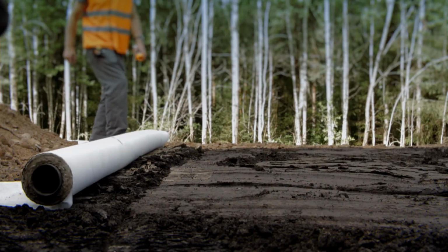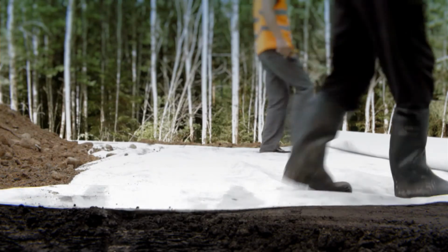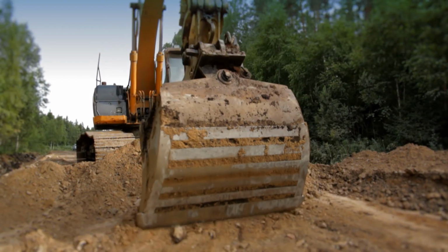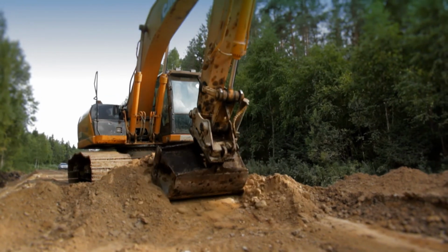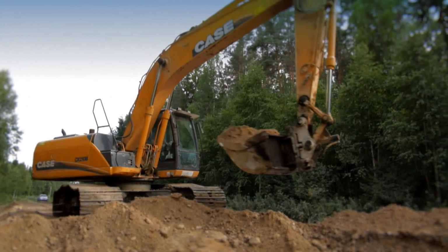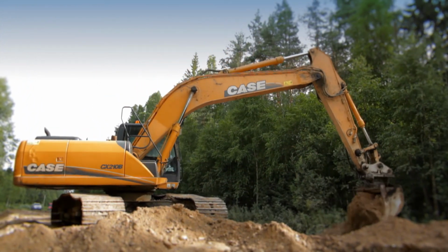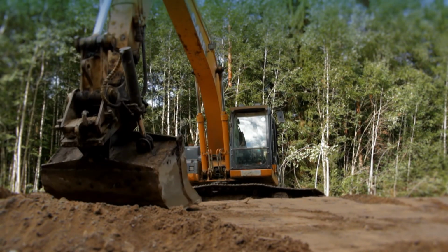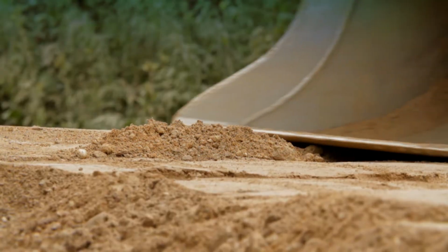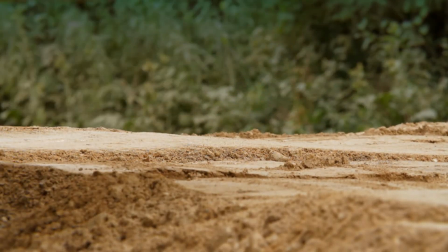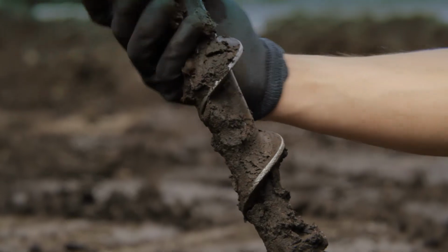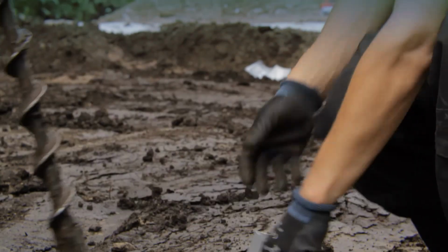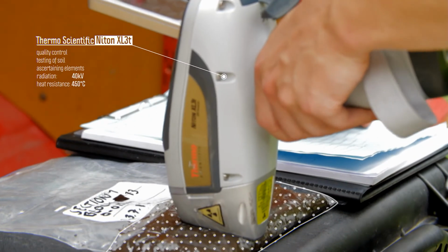A geotextile which separates different layers from one another was laid on the peat, which had been stabilized by the ash mixture. As a last stage, load layers were constructed with the purpose of compressing the stabilized subsoil. At the same time, they worked to separate excessive moisture from the stabilized layer and accelerate the strengthening of the treated subsoil. Throughout the project, tests were undertaken and measurements were made to compare the efficiency of different combinations of the mixtures.